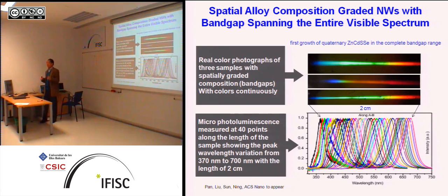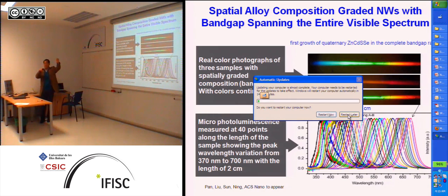So over 200 nanometer spatially tunable, and this is even more impressive. I didn't mention the materials we used were from cadmium sulfide to cadmium selenide. When we got this 500 to 700 nanometer tunability, our program was supported by the Army Research Office, and the program manager said, can you do UV? I said, sure. You look at the band gap versus lattice constant, the standard semiconductor chart, and see what other wider gap materials you have. We quickly realized that zinc sulfide, for example, can be composition graded with cadmium sulfide.